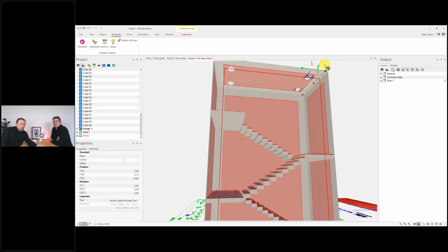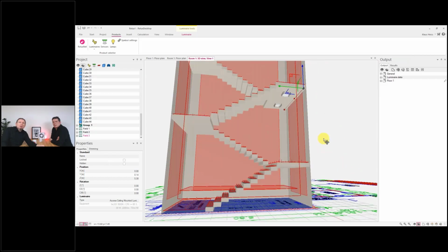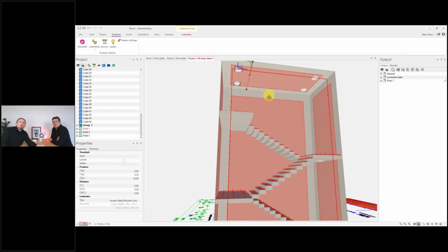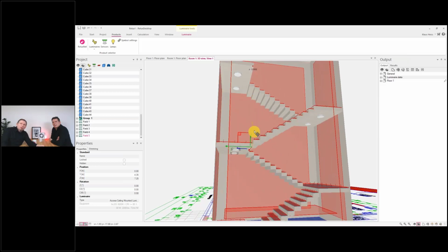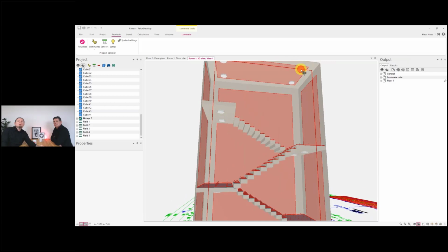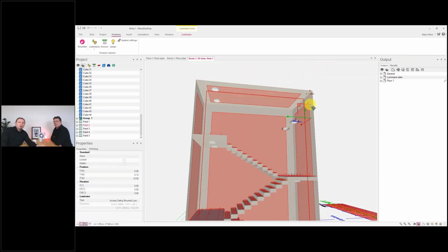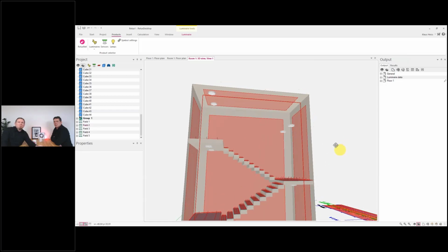And here I'm also going to use the control button again and just put down these 2 luminaires in this region. Here I don't need any lights, and here these luminaires should also be copied to this area for the first floor and once more for the ground floor. If you do these luminaires right on the first floor, then you can also copy the luminaire together with the stairs to above. And these luminaires we need to lower a bit without a copy, just to have more lights in it, and we need to suspend it in this area.